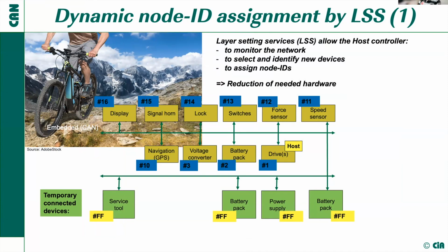for CANopen FD, we have extended this also to network ID assignment. It works one-to-one as the node ID assignment. So therefore, in all the slides, mainly I talk about node ID assignment, but you can apply all that, what I say, also to the network ID assignment.